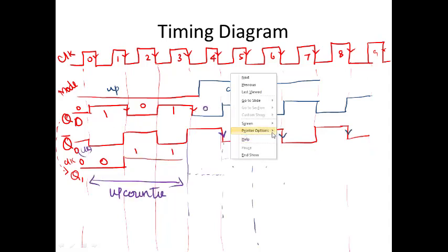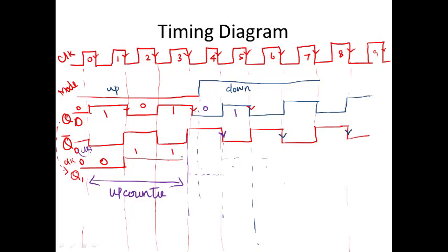I am giving my mode bit 1 here, okay, 1 here, so here only. So if you look at it here, the clock edge is here, so it will be 0 now, but here your mode is going to be high, so this Q1 will be retained at 0 till my next clock edge.